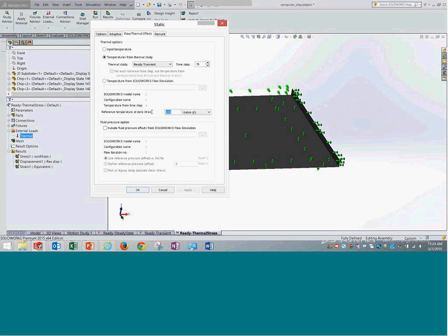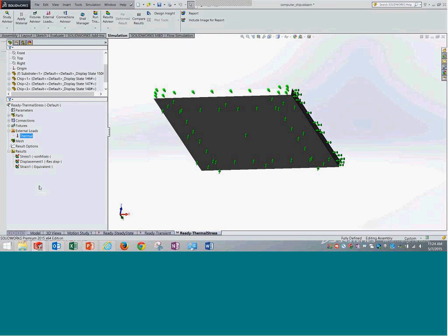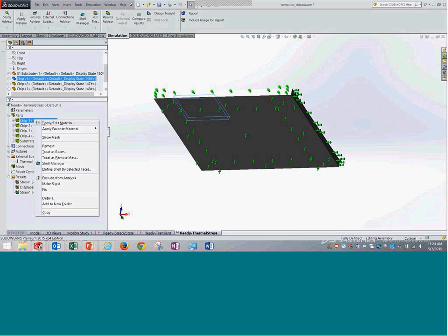Finally, the initial strain or zero strain condition is 300 Kelvin. That is, the part starts at 300 Kelvin, wherein the strains are zero. Thereon, it is subjected to the temperatures which come from the transient analysis. And when the temperature is increased, we are seeing the increase in the length of the part.